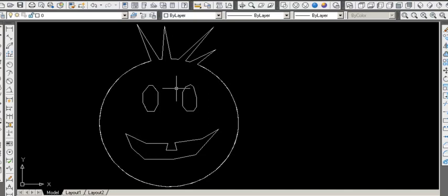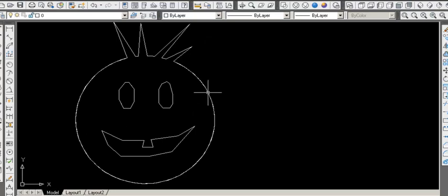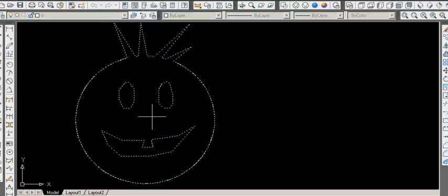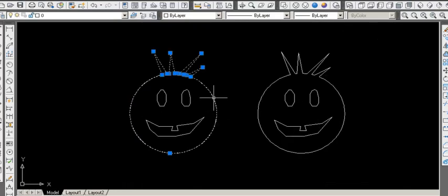The boundary command takes whatever you draw and then just basically traces an outline around each component. So for example, when I click once here, click once here, click here, click here, and use my move command, just my good old-fashioned move, to move it from here to here, you're seeing the original geometry. In fact, there's probably several of them because I did the boundary command so many times. Right now I'm actually hitting delete and deleting away the original geometry.